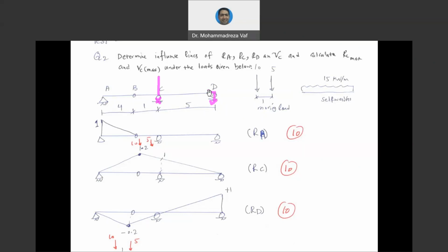Therefore, we are going to see for the right side this displaced shape like the one that I draw here. For the left side, we have point B here that has a hinge and point A. So if point B wants to go up, we should see whether the adjacent point allows it or not. As you can see, we have only one pin support over there, and point B can easily move toward up as point C moves because it can rotate.